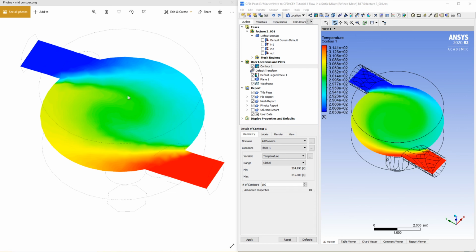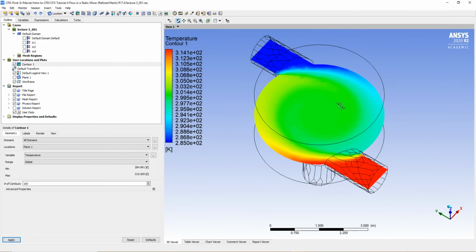Okay, the temperature, especially in the middle, should be more uniform, and this is something that we can see better in the more refined mesh. I'm going to make it bigger here. So you can already tell that only by changing the advection scheme and the mesh quality, we already achieved much better results.